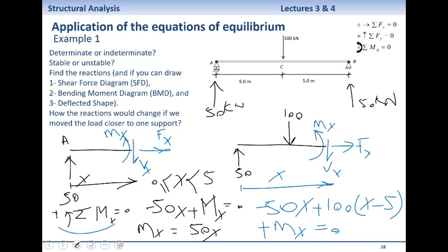And one thing that you need to know is that we never ever cut a beam right where a force is. Out of the infinite number of points that we have, there are specific points that we do not use to write the equilibrium because they are not helpful. First of all, any force has got a bearing area, so they are not applied at one point.